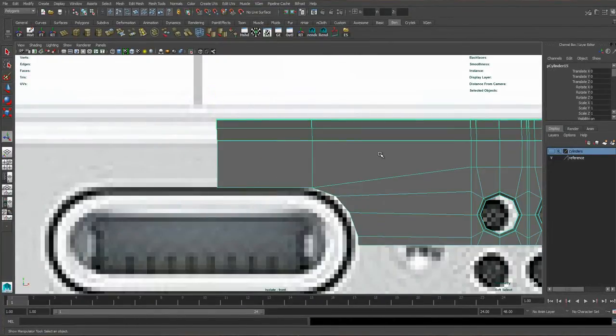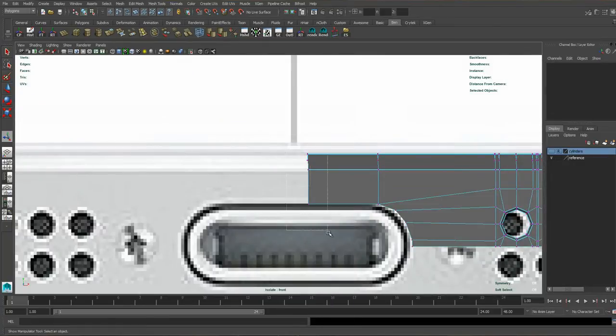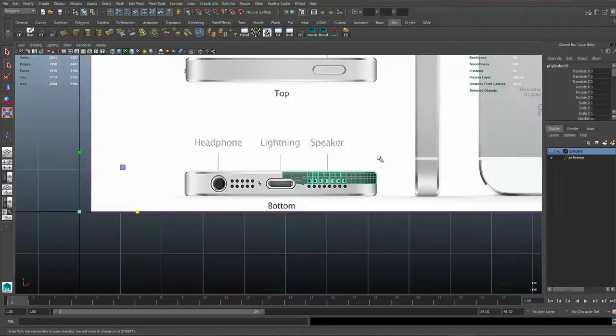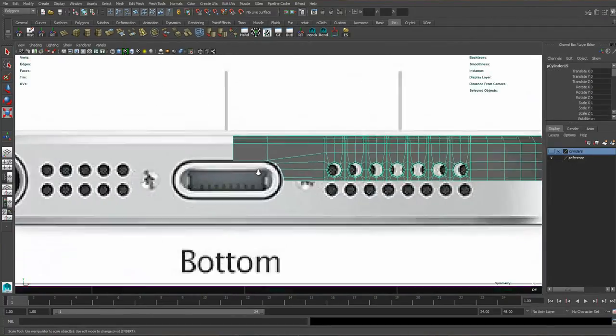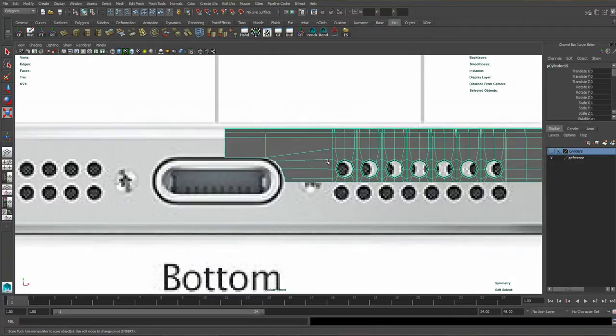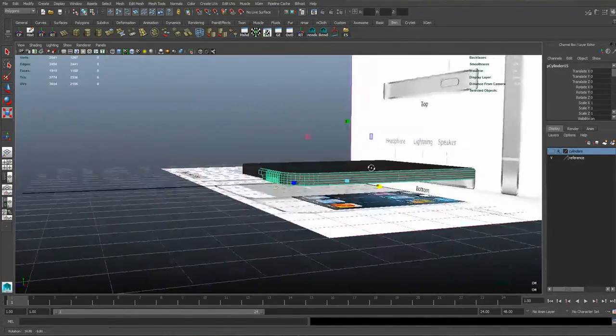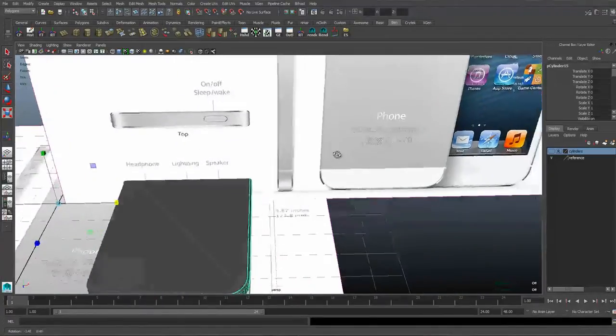And so it should look like this now. And I'm going to just select these vertices in the middle and resize them so they are completely flat against the camera like that, which means we can mirror them quite easily later on. So the geometry should be looking like this now, and we should be ready to flip over the minus y-axis.